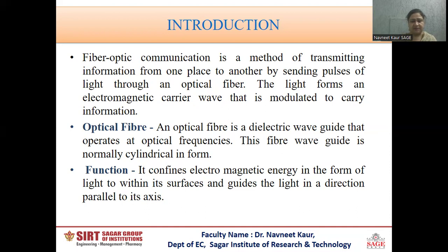Now, what is an optical fiber? Optical fiber is a dielectric waveguide that operates at optical frequencies. This fiber waveguide is normally cylindrical in form, in which the signal is propagated in the form of a light wave. Now, what is the function of this optical fiber? It confines electromagnetic energy in the form of light within its surfaces and guides the light in a direction parallel to its axis.